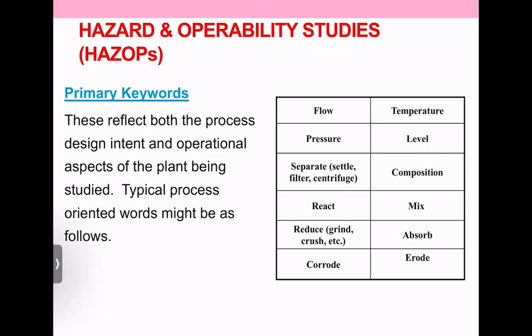But as a start, when you do not know what to do as a fresh engineer, if you do not have a senior to guide you on what to look at, always go with the basics: flow, temperature, pressure, level, composition. You will never go wrong. The rest is a little bit higher level and requires experience in the process and knowledge in the chemical reactions. Any questions so far?